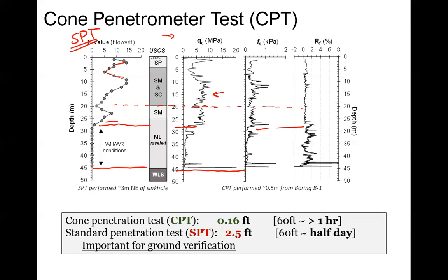The issue with cone penetration tests, though, is that we don't get a sample. This is the one pitfall with this test. We don't get a physical sample. So we get a lot of data. We get friction ratio. We get all of these different data. We can get pore water pressure with it. We can equip this probe with a bunch of other tools, but we don't get a physical soil sample to do other tests on. So that's the limitation with this. It's a give and take.